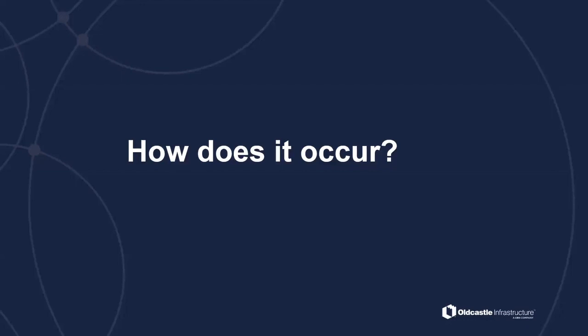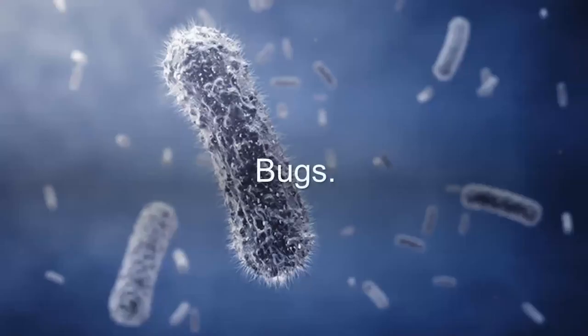It's not true. Okay, so how does it occur? Well, this is a pretty fascinating topic and a conversation of how this occurs. And simply put, it comes down to bugs. All right. This is a bacterial process. Now, for years, we relied on some ASTM tests and acid resistance tests through ASTM. We relied on ACI 201 for durability of concrete. But these specifications don't address MIC because MIC is a bacterial process and it involves these bugs.